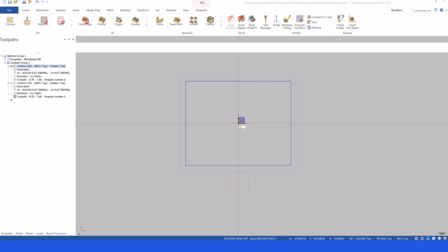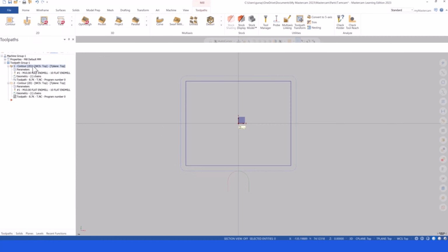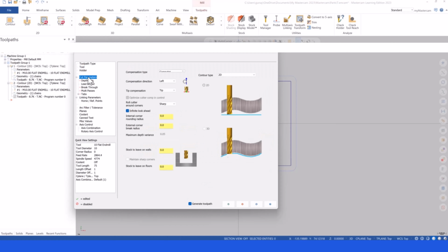So we're gonna start from the maximum chip thickness here. We are rotating in that direction. This is maximum to minimum and maximum to minimum. So we can easily handle that by using our cut parameters, compensation type calculated by the computer, and we're gonna be on the left side.